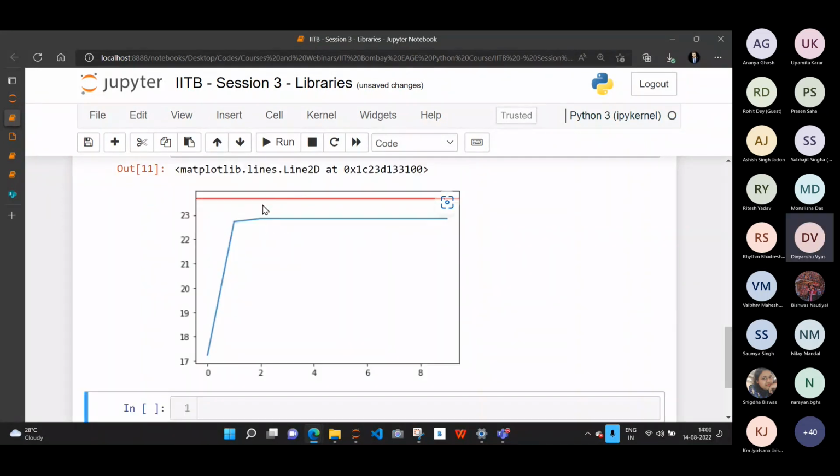So you can see, yes, we are a bit far away, but the Newton-Raphson's method will not get you any further. So basically, there was no need to provide you 1,000 iterations. You could have done that in only 8 iterations. Even on the fourth iteration, the Newton-Raphson's method could have just concluded. And I remember from Tariq Ahmed, the textbook, they solved this entire thing in 3 iterations, which means we did not even need the fourth iteration, as is clearly evident from the plot.